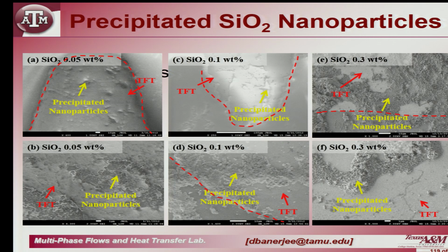What does that mean? That means the thermal properties of the nanofluid are secondary. It's the nanofins that are dominating the game, because once the nanofins form, it doesn't matter whether you are flowing pure water or nanofluid, you are getting the same heat transfer. So that means the nanofin formation is the more dominant mechanism here. A simple experiment gives you so much insights, right?